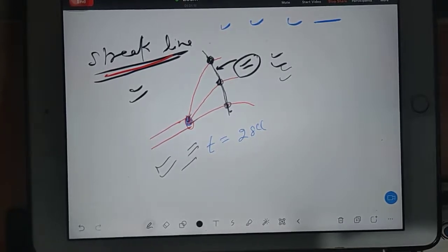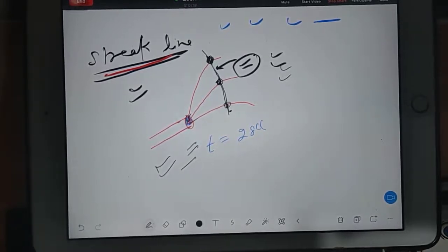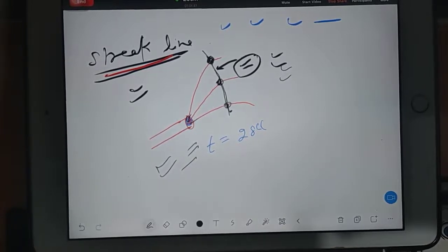Yeah, in real life, any flow you cannot consider as incompressible, because density will change for sure. In real life, you cannot say that your flow is irrotational. Every time flow is rotational, because you have viscosity. Viscosity means friction. Any time, assumptions will not work. In reality, when you say okay, flow is in 1D, no, flow is never in 1D. Flow is in 3D in real life.